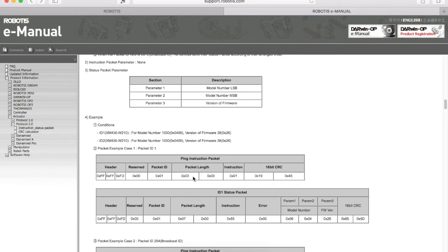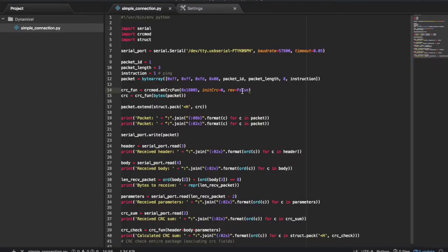As it's coming in, as I said, we're reading and then we get the lowest portion first. But actually, the way that this is implemented is that we get the entire packet and then we do the CRC check on it. So that's why we say we're not doing it in the reverse order. Okay, if you didn't get it, that's okay, but this is the way to create the CRC function.